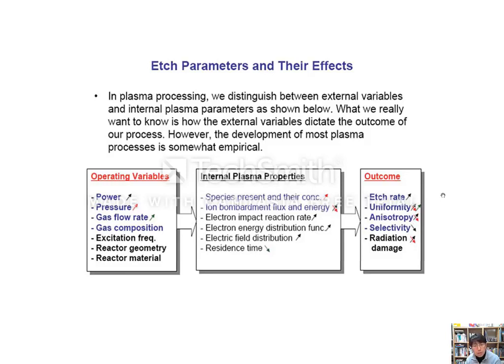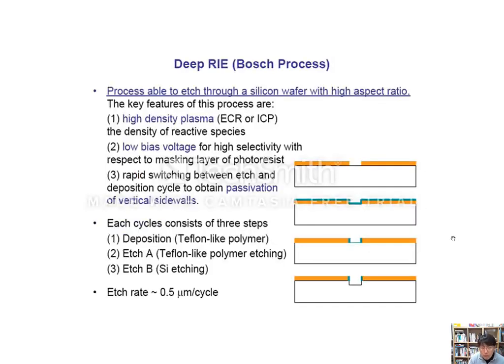If you don't like the etch rate and you want to increase it, then try to push the power up. But after pushing the power up, maybe your selectivity goes down, or you have an unwanted N asterisk going up. Then what you can do is push the pressure up, and then the N asterisk will go down. So those are the kinds of combinations you can play with to get the optimal recipe. Okay, let me stop here and let's continue to the next slide.